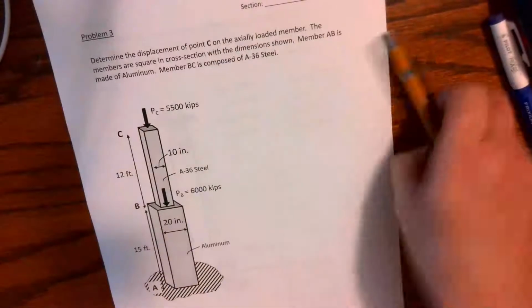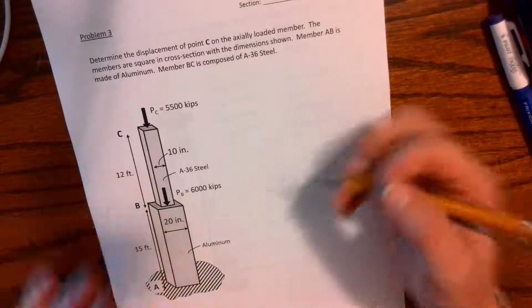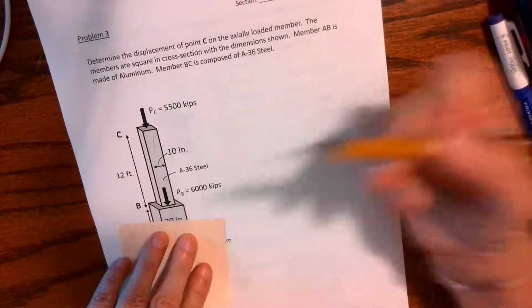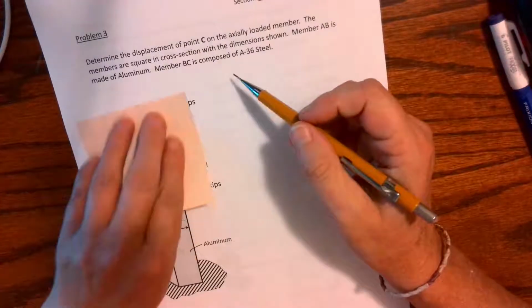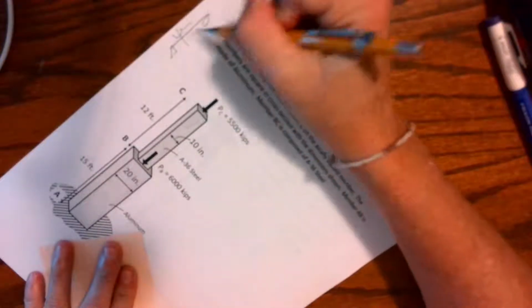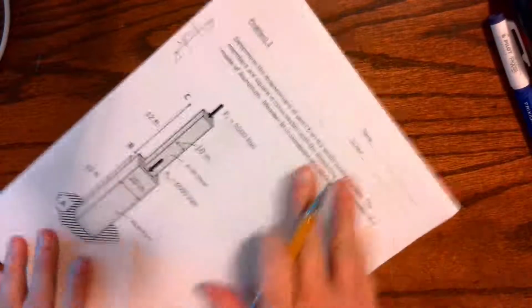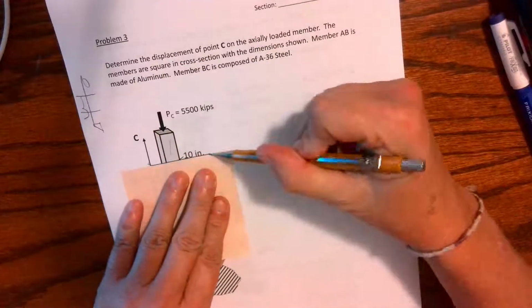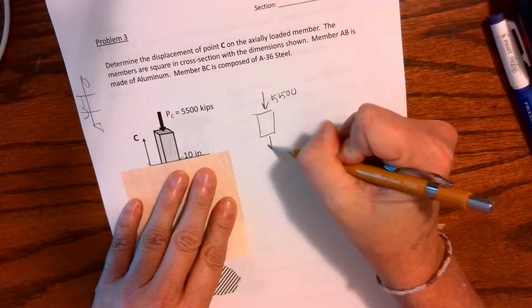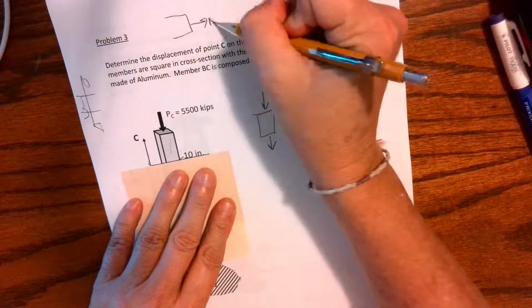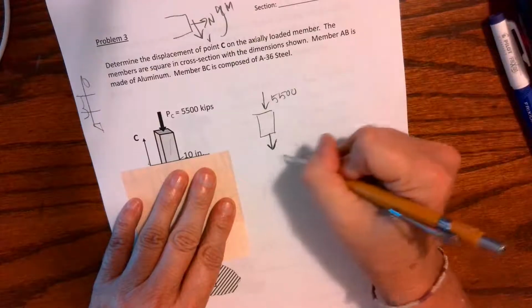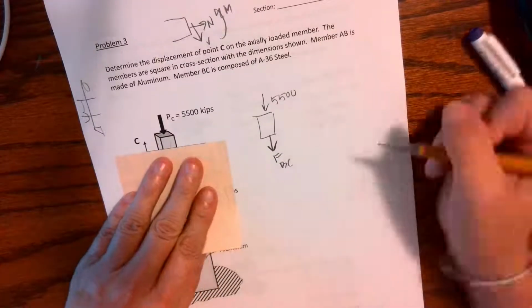Okay, the cake problem. The first thing is, you all have got to get yourself a Post-it note, okay? If I want to find anything, deformation, stress, whatever it is, I have to, just like statics when we had a beam and we loaded it, we had to draw our shear and moment diagram between where we had loads. So I'm going to come down, I'm going to cut it there, and I'm going to draw myself a free body diagram of 5,500 that's given, and I always assume tension. What are our internal forces? Normal, shear, moment. Okay, here's my normal. It's my force from B to C. I'm going to assume it's in tension.